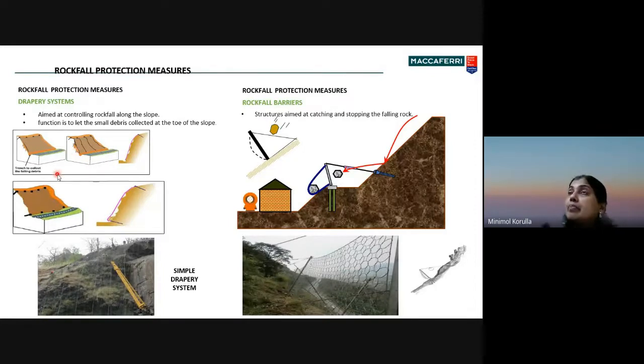So this all depends on the type of the rock slope and what the detachment level is, or the fissures, joints, or faults. So that type of deep study is there. By this time you may have clarity that to analyze the rock types, we may have to take the help of a geologist.